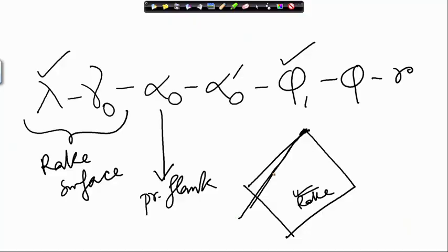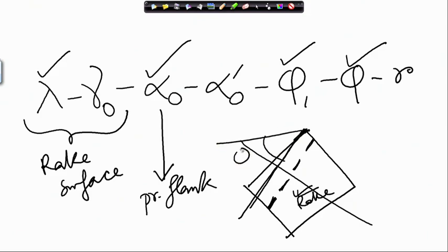From the main cutting edge, okay, in this direction I get the incline of the principal flank. I cannot see it from this side. I get the incline of the principal flank by this angle. So, I use this up also. I made a mistake. Phi is used for getting the inclination of the cutting edge. Just a moment, let me rub off some of those unnecessary lines.